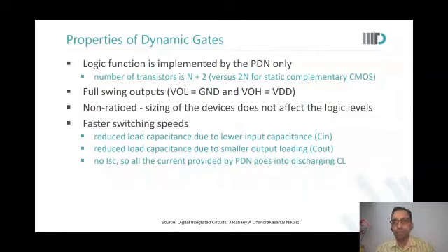But the dynamic gate will always have a 1 to 0 transition at the output. Right? Yes, because at the end of the cycle, you had recharged it to 1. So if the output has to transition, it will always be from 1 to 0. There is no other transition possible. It was already 1. It can only go to 0 now, or it will remain as 1. When it remains as 1, what do we say it is? Floating. Yes, sir.